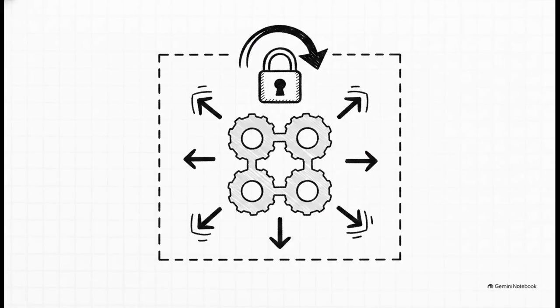We've got to audit this lower segment, the FRTZF, against some very strict ASME rules. If datum references are repeated in the lower segment, they must be in the exact same order of precedence as the upper segment. But crucially, the datums in the lower segment only constrain rotation. They cannot constrain translation. So this means the tighter feature relating zone can literally float around, translating totally freely within the larger pattern locating zone, but its rotational orientation is strictly locked to those repeated datums.